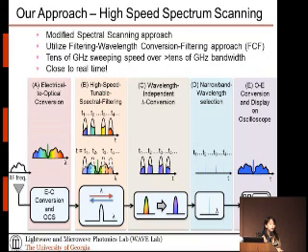So we have the RF signal here. We do an electrical to optical conversion, just like what we did before. And then we use a relatively broadband filter, but it can be tuned at very high speed because it's all-optical tuning. So it can tune at tens of gigahertz speed to chop out each of the components. And then we do a wavelength independent wavelength conversion here. So all these different colors will eventually convert to the same color here.